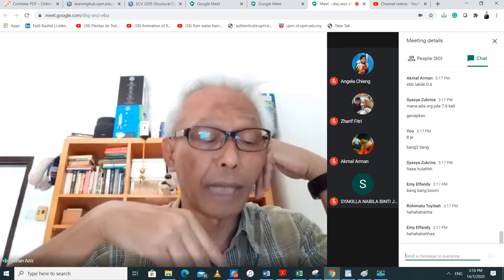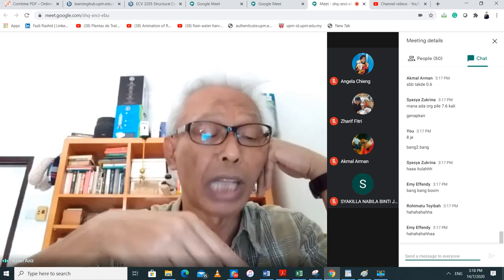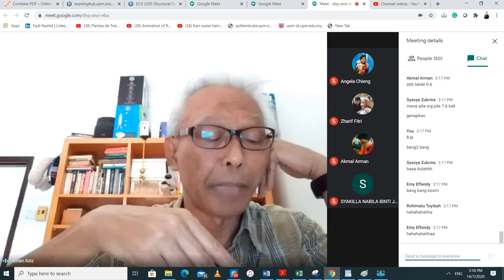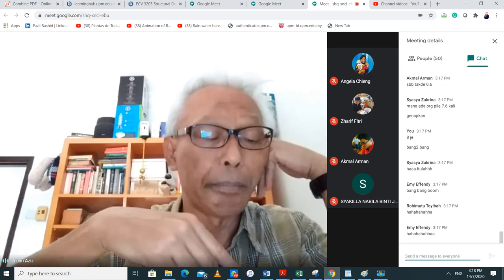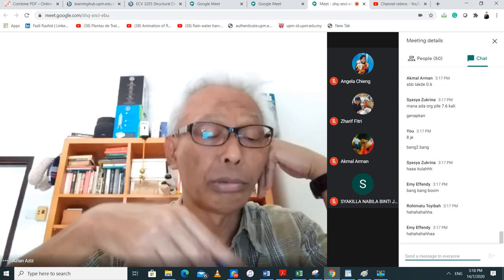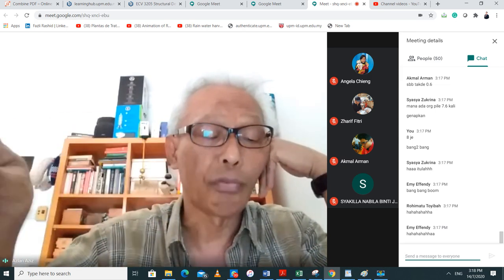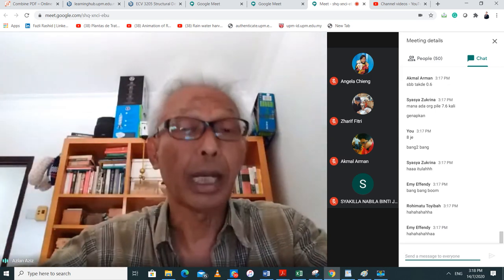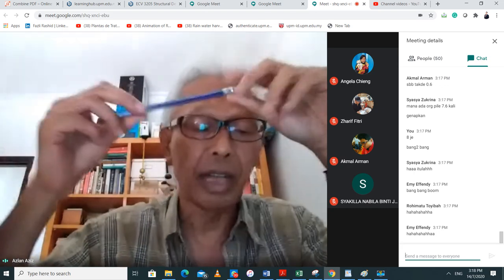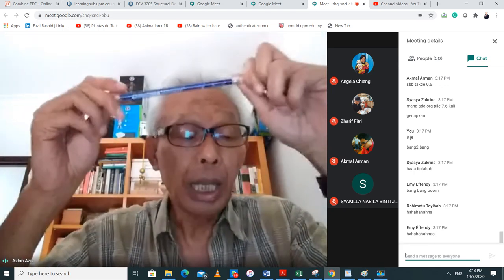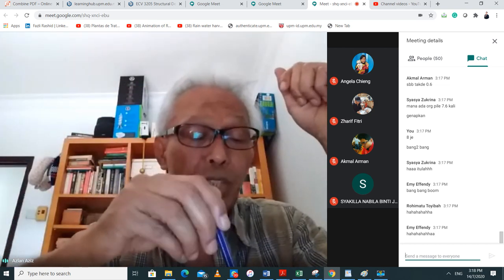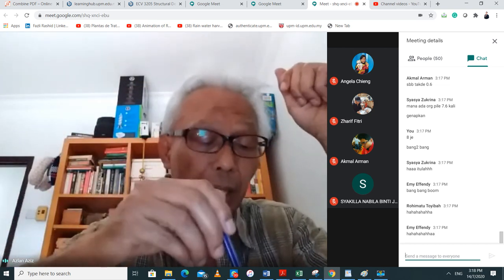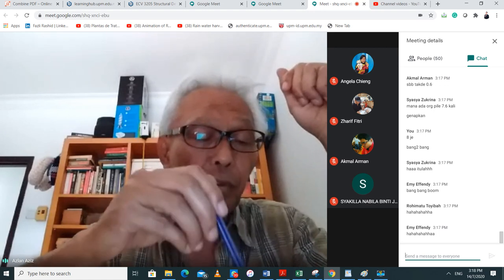So you get for the first one 2, 2, 2, 4 times 0.45, multiplied by D sub B, which is 1.5, multiplied by 2 N bar. N bar is equal to 4. So you get 22. You can calculate that yourself. And then you use Meyerhof. The first row of Meyerhof is 40 Q sub F. This is the tip resistance. 40 divided by 0.45 and D sub B.